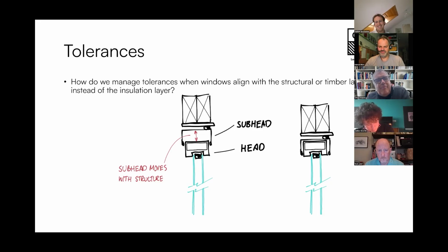Look at Marcel. Yeah. They actually place a window frame without the moving parts and the glass in the wall while it is constructed, which means they get rid of the tolerance problem by having the window placed and then the brick brought next to it, which I think is a smart way of doing, because then you have a soft part which is then hardening in process, which is brought to the window, and then you place the window frame with the openable parts later into it.